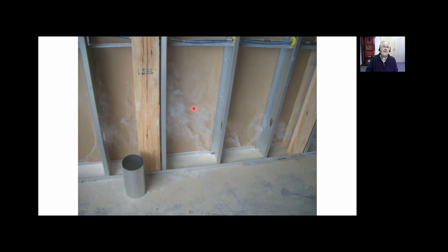Here the same technique was used, but now they're laying this blanket of fog down at the bottom of a wall on the other side of this wall to see if the drywall is sealed to the bottom track of this metal stud wall, and of course you can see here that it's not sealed very well. And this is where somebody that wonders, does this really matter? When they see the fog, it kind of makes believers of people.